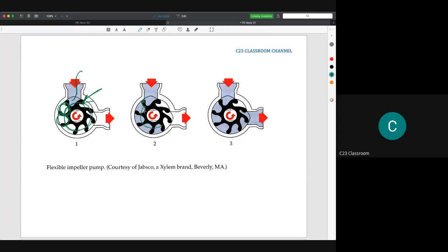In a positive displacement pump, we don't have manometric efficiency like a centrifugal pump, because the main idea is we are transferring the water by volume, volumetric here. The important thing is we must make sure that each space here is really tight, so the water is not leaking.